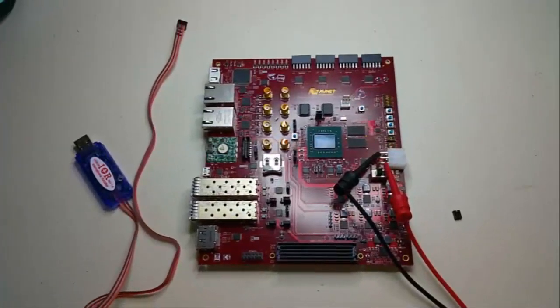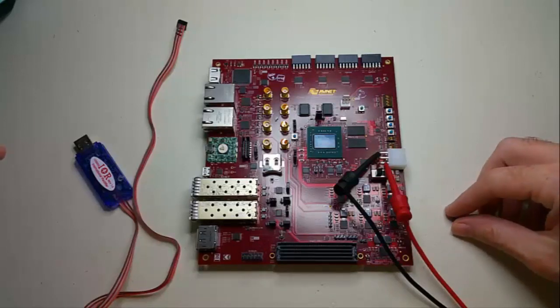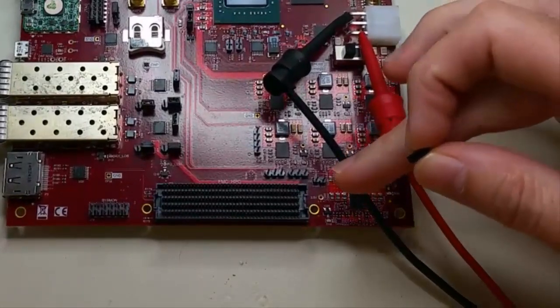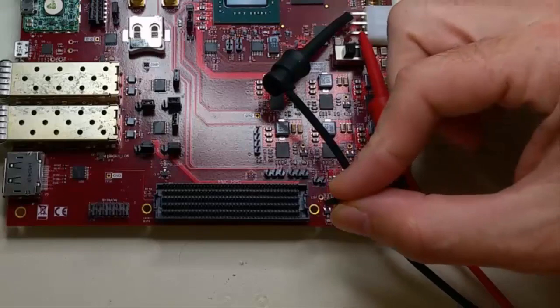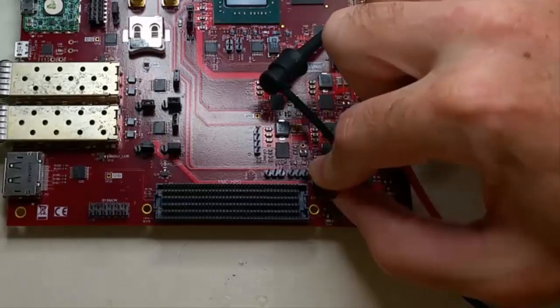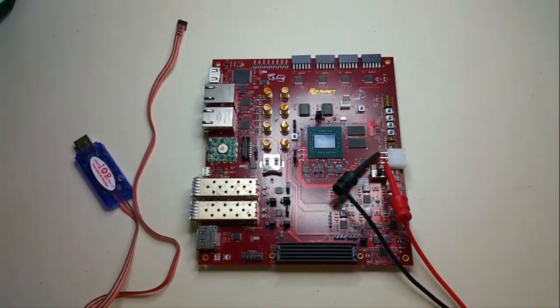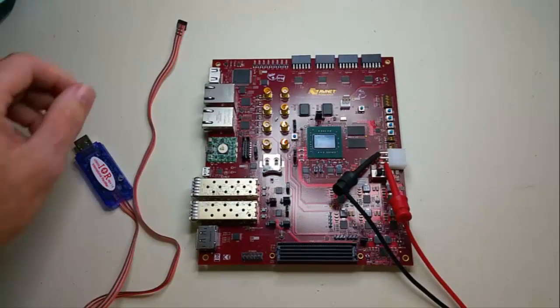So here's our UltraScale board. Now the first time you power up this board, the devices, before they're programmed, default to come up at 0.5 volts. Now in a lot of applications that's not going to be a problem because it's typically going to be too low for any of the devices to try to start up. But for safety and for our startup procedure, we provided this 2-pin header right here that you can short to ground, which will disable all of the outputs on all the regulators. So the first thing we do, the first time we powered up this board, is to disable all the regulators.